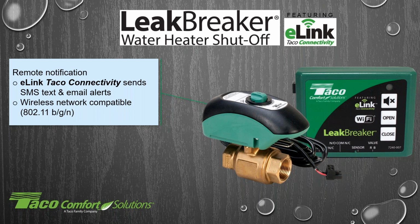You would not want to be sitting at the beach on vacation, look at your phone and say, oh, my valve is closed, well, maybe I should go ahead and hit it back open again without inspecting. That we don't do. You have to go back, go downstairs, and inspect to see why there was an activation. Then you silence the alarm, dry off the sensor if it happened to be a false activation, and then hit the open button on the controller. But now we have added this E-Link connectivity.